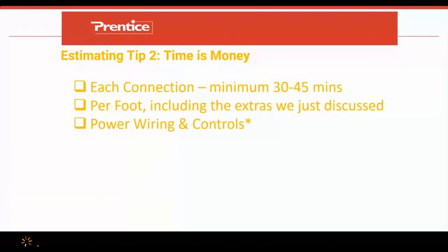All right, estimating tip number 2. Time is money. Hey, we know that, your estimations are important to get right. And if you're not taking into consideration how much time, how much man hour it's going to take for every connection, and you're just basing your man hours on the amount of linear footage that I have, then you may be cutting yourself short. So I like to recommend a minimum of 30 to 45 minutes per connection, and that includes the power connection kit, NETs, as well as your end seal.